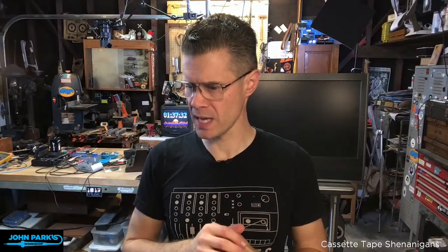And then I think it's actually easier to set up something like MIDI than it would be the control voltage, because a control voltage coming off of something like Eurorack can be anywhere from negative to positive 10 volts. So there's a little bit more circuitry needed to bring that in and then convert that to resistance values of the digital potentiometer, but it's totally doable. I'm not sure about gates, because often a gate impulse could be used. You could use that maybe to just do a full stop or some kind of a muting of the player, so it might be neat to have both gate and control voltage in there.